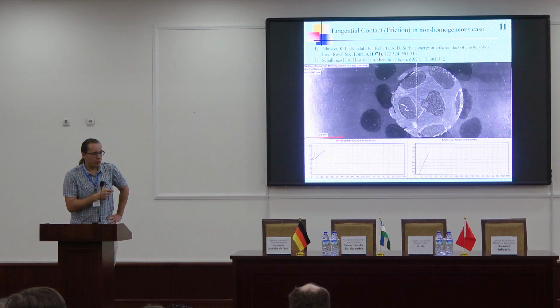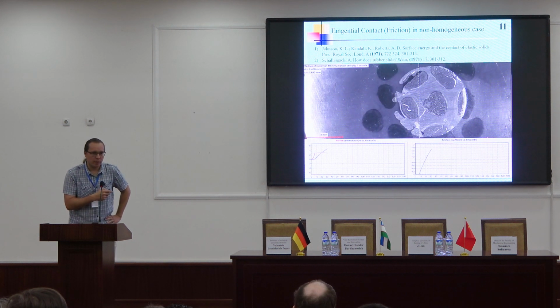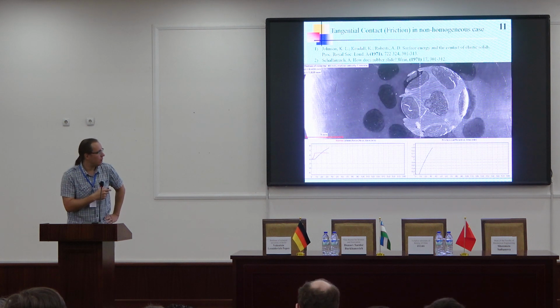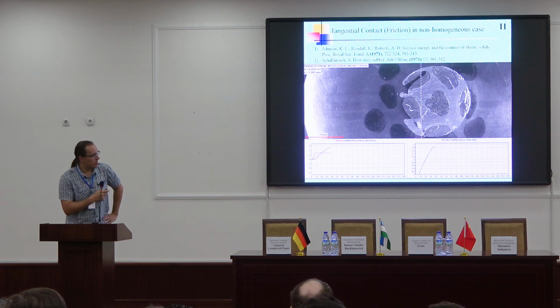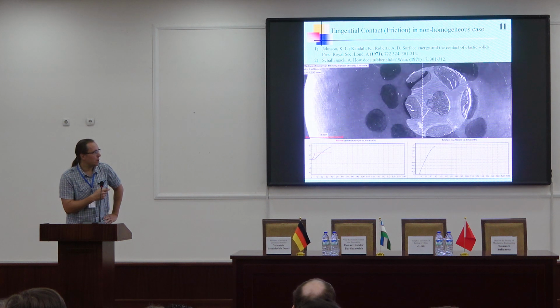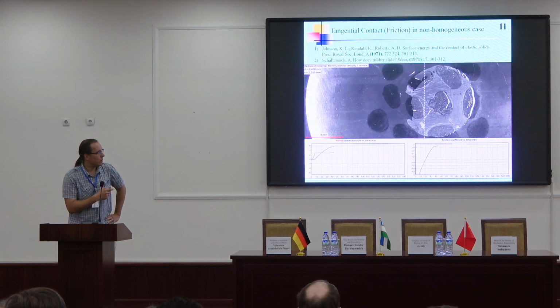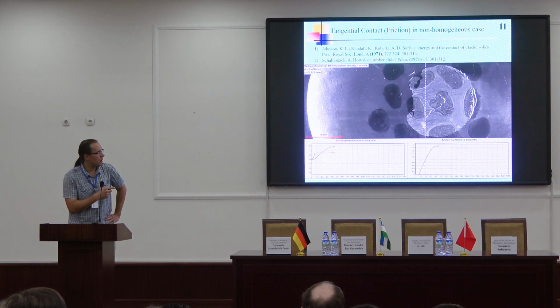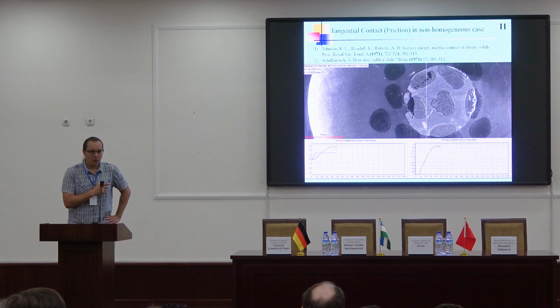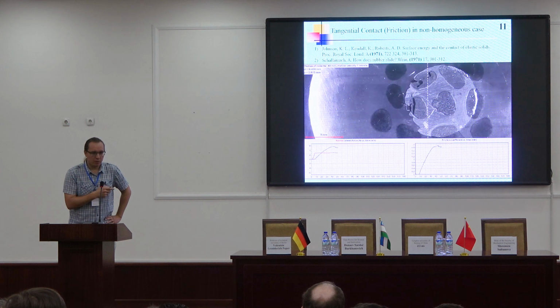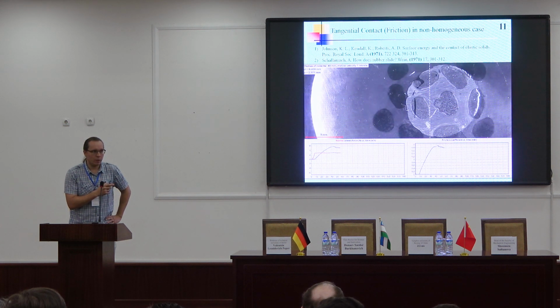And you can observe here very difficult and, I would say, very strange processes in the contact. It's something like elastic wave propagation, and we have bigger velocities of these elastic waves at the areas with bigger adhesive strengths, because at these areas we need to apply much more tangential stress before the beginning of sliding.